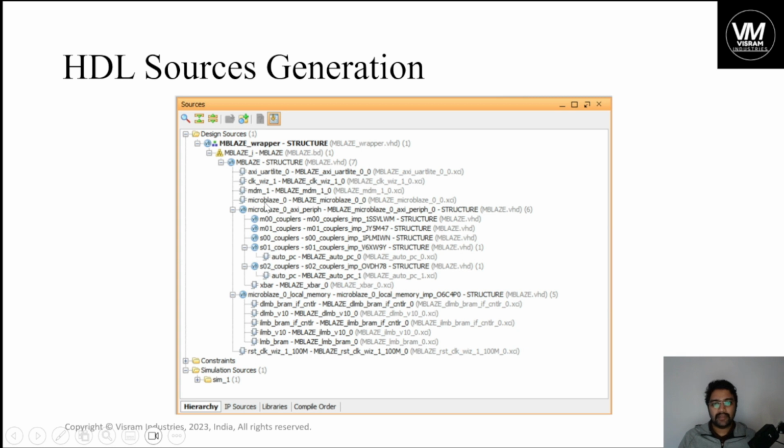How did it prepare these VHDLs in a click of a second? It's very easy, guys. That is automation. Those are already there in the IP integrator. Those are brought by the EDA tool to us based on our connections, based on our configurations on Clock Wizard, based on the architecture we design with every other thing.